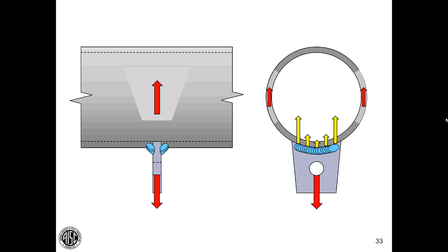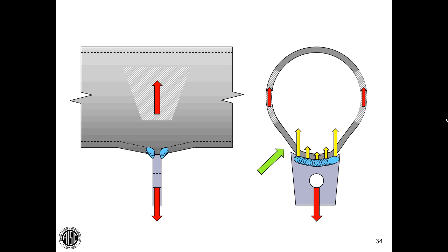And the deformed state helps us understand what's being strained. Do you see the strains at the weld toes and the strains at the end of the lengths of those welds? That's the problem with this orientation as well.